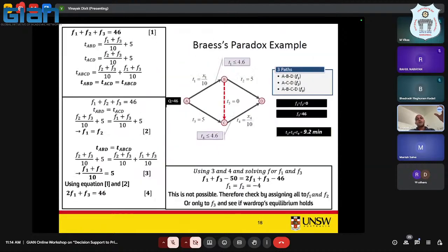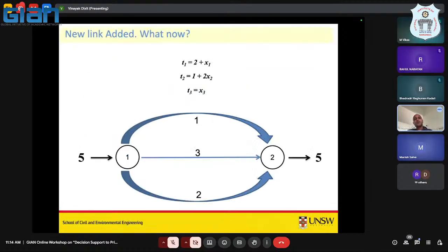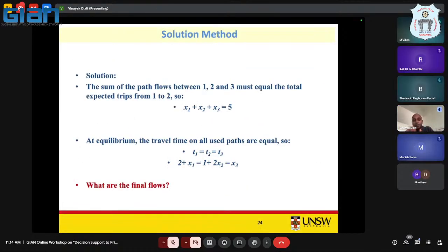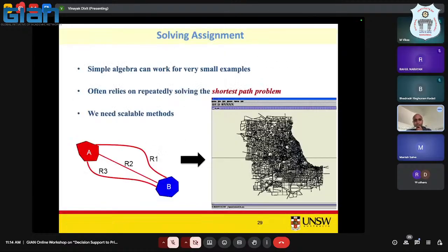And that's how you want to be thinking about it. Then you ask the question, okay, the differences in all of these models are only in the link performance functions. So in which type of project do I need what type of link performance function? That's the question you should be asking. So when you're doing small intersections, small pieces of cities, you use microscopic because you want to pick up on the interaction. Correct? Yes.